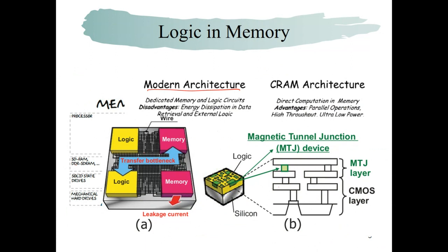The difficulty is that in a DRAM, as you remember, there is a large, very deep trench that requires another technology, so it cannot be combined with the CPU. It's a totally different process, but MRAM or STT-RAM can be combined with this logic process. So if you can make a combined logic and memory, we can make a much better and much faster CPU. That's one of the main approaches.